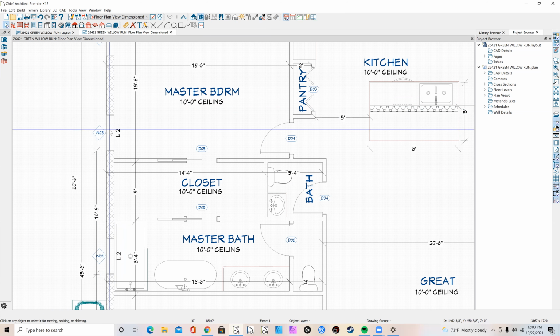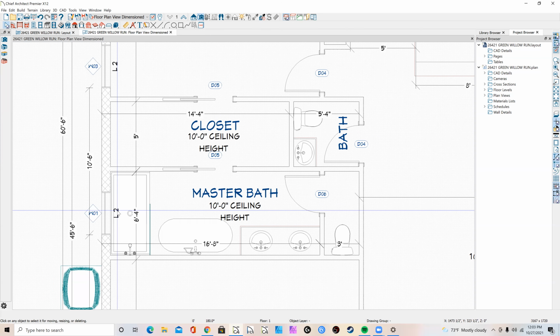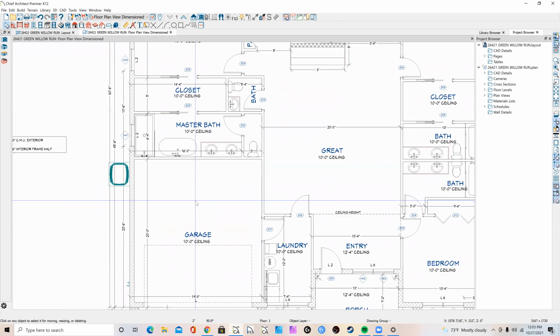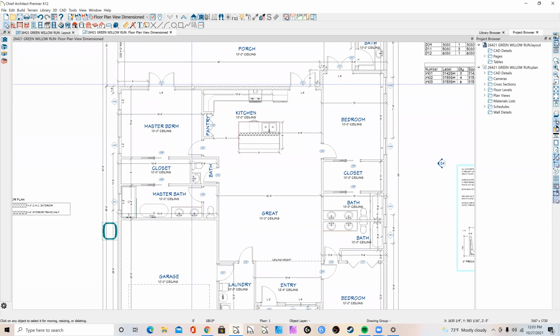Remember we were talking about lintels that go over windows and doors? This is how we know which lintel goes there. We need to mark it on every opening: the garage door, every window, and every exterior door. Interior doors don't matter because they're not made out of concrete.